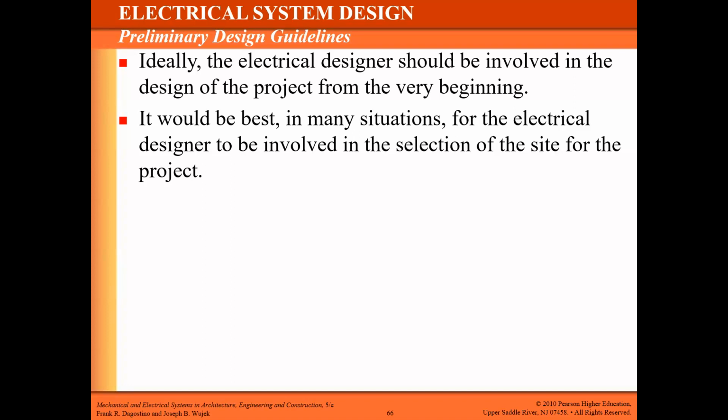And then, of course, it's always good to ask the question about the possibility of future expansion. If we size our main electrical system for just what we need today, even if we know we're going to expand and put a big addition onto this thing in 10 years, it's generally not a good idea. So we want to make sure that we're accommodating to the extent possible and to the extent that's affordable all the future expansion that might be necessary.